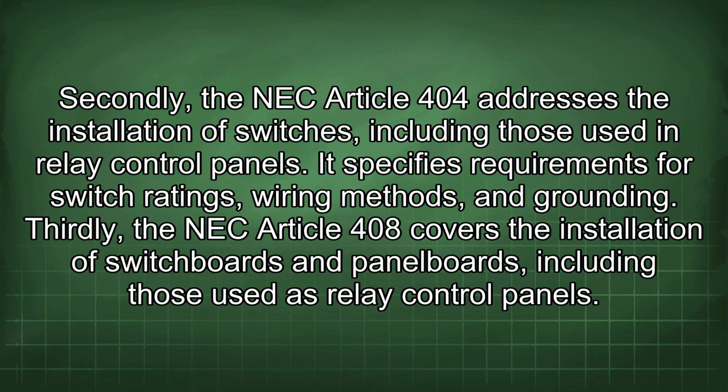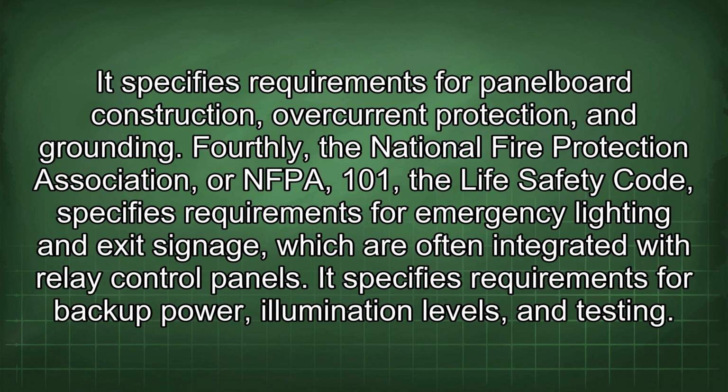Secondly, the NEC Article 404 addresses the installation of switches, including those used in relay control panels. It specifies requirements for switch ratings, wiring methods, and grounding. Thirdly, the NEC Article 408 covers the installation of switchboards and panelboards, including those used as relay control panels. It specifies requirements for panelboard construction, overcurrent protection, and grounding.